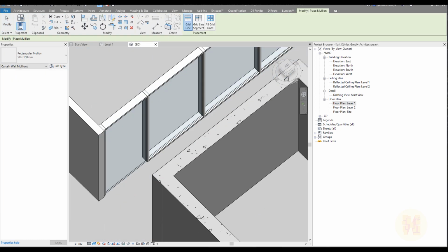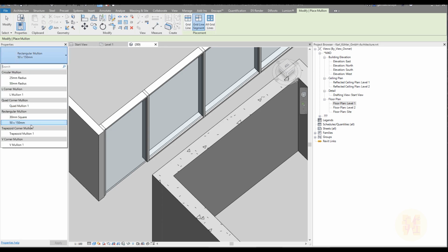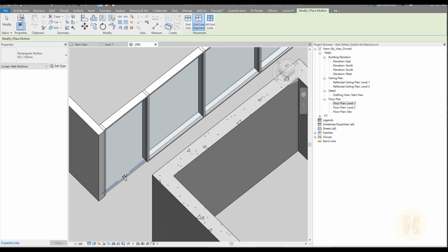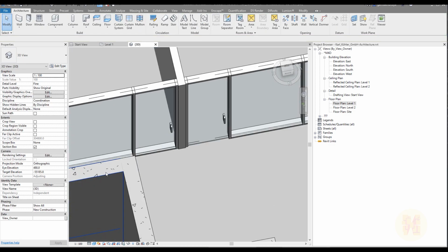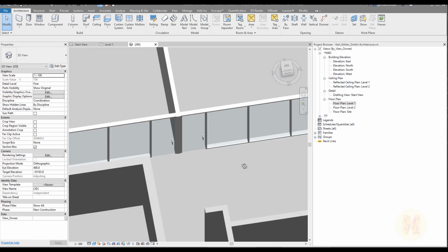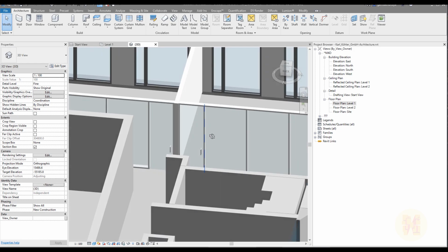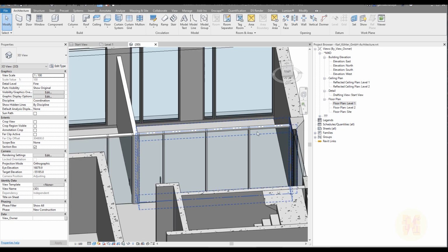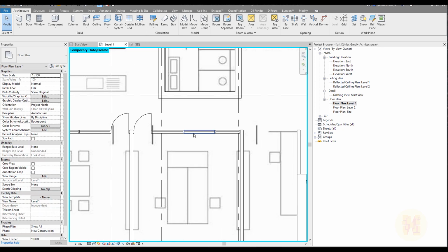For that one, just go to the mullion, one segment, and choose this same type, 550 to the 150, and select this empty part. Here you should delete it. Unpin it, delete. So as you can see, it's pretty long work, but once you finish your interior part.